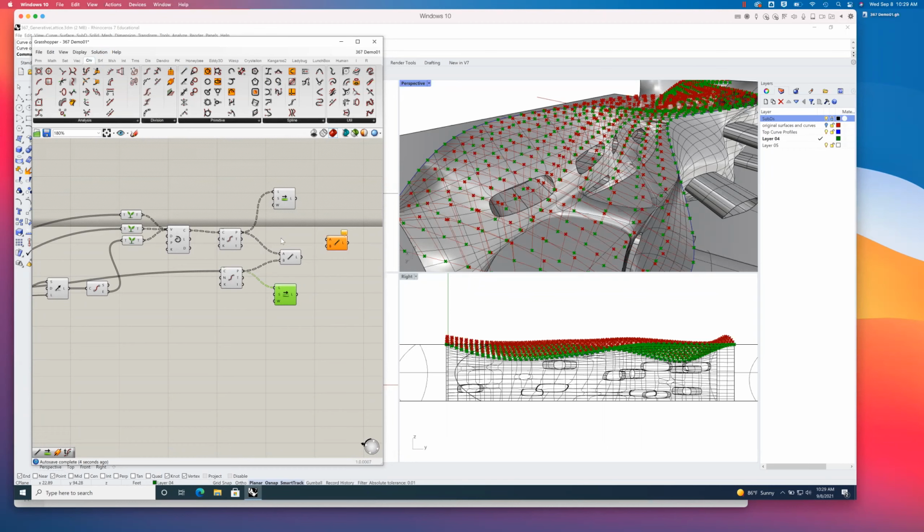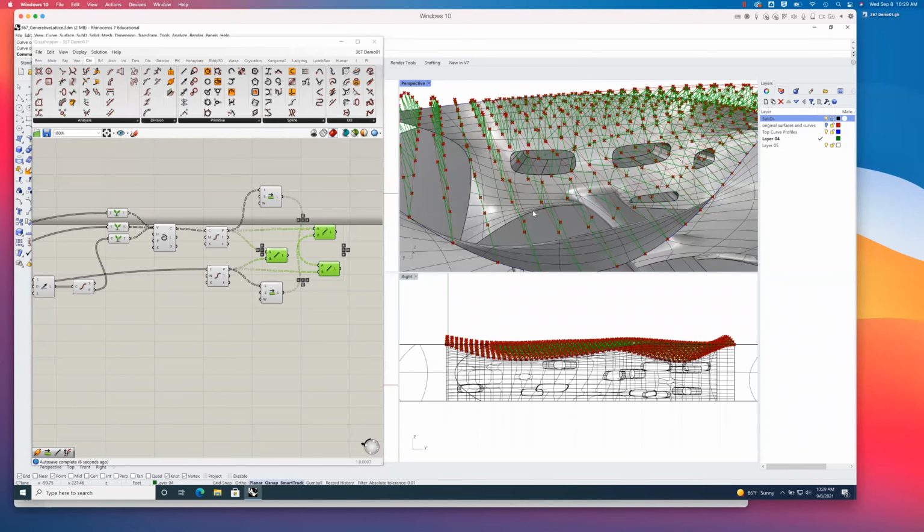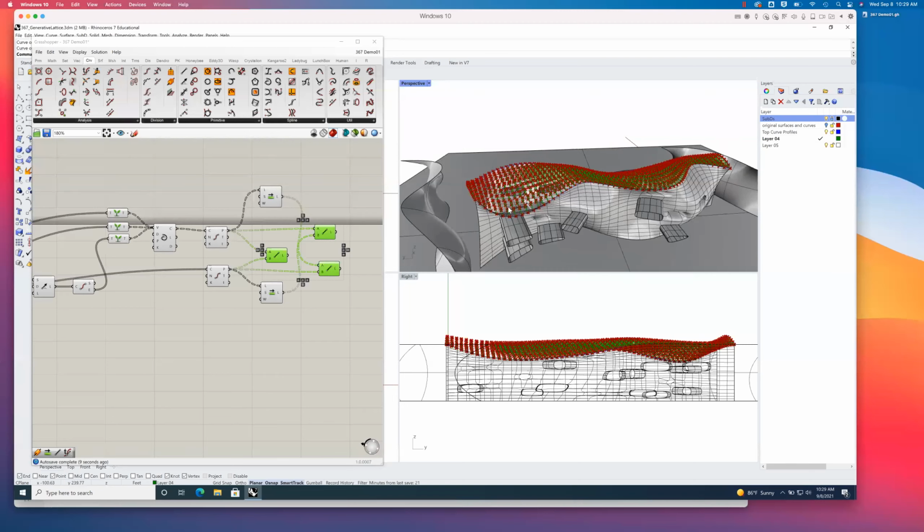I'm just going to make the crisscrossing diagonals. I'm going to take this list of points and then the shifted list of other points. There we go. Oh yeah, look at that. Wrap was set to true, so I'm just going to turn that to false. Wrap over here also set to true. Set those to false. Okay, I'm going to make another set of lines. We're just connecting the dots here. This shifted list with this unshifted list. Oh yeah, look at that. All right. Now we have a set of trusses. All right. Okay.